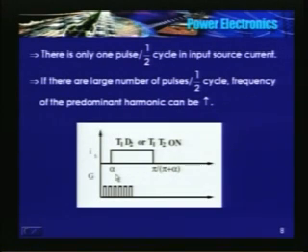It is alpha by 2 for a half controlled bridge, and alpha for a fully controlled bridge. So if I have to improve the power factor, I need to make alpha equal to 0. Conduction should start at the positive zero crossing. I am reducing the harmonic content, in other words, I am reducing the THD. So it implies that my fundamental component is the same as IRMS, I am improving the power factor.